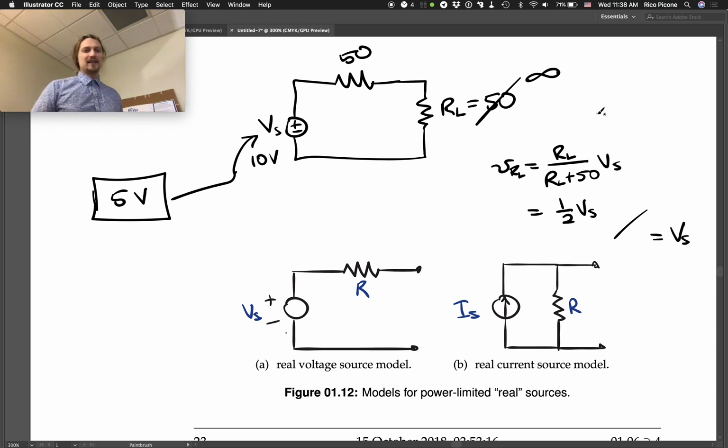A nuance to this is that our function generators, most of them, the newer ones, they're fancy, okay? They have a fancy setting called the high Z, high impedance setting. And what that does, as far as I can tell, is it just says, okay, instead of assuming 50 ohms, we're going to assume it's a high impedance load. And if you say 5 volts, we'll put 5 volts here. So that's my understanding of the high Z mode.